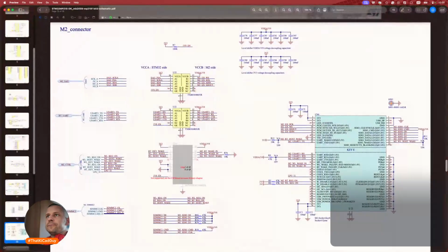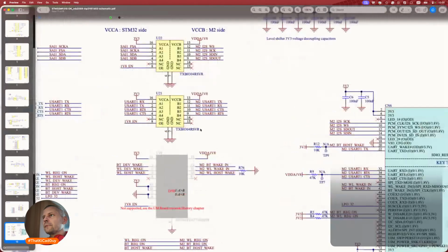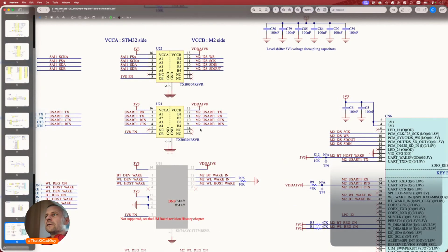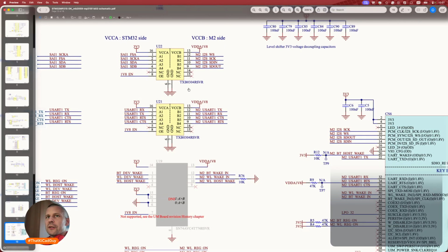And here is control SD MMC. Yeah, here are level translators, but I'm curious why. Okay, probably from the PCB layout perspective it was better to use two packages instead of one 8-port package. Yeah, that makes sense.